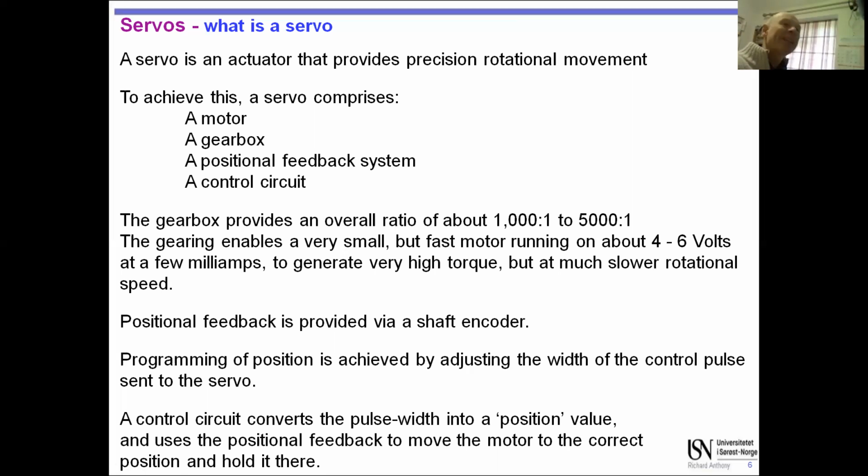We also have magnetic shaft encoders, where you basically detect a series of magnetic pulses. Imagine you have a cog, and you have a magnetic detector here. As the cog rotates, anything ferrous metal going past, you detect pulses as it goes past the sensor. As the wheel goes past, you detect it, and you know how far it's been turned.